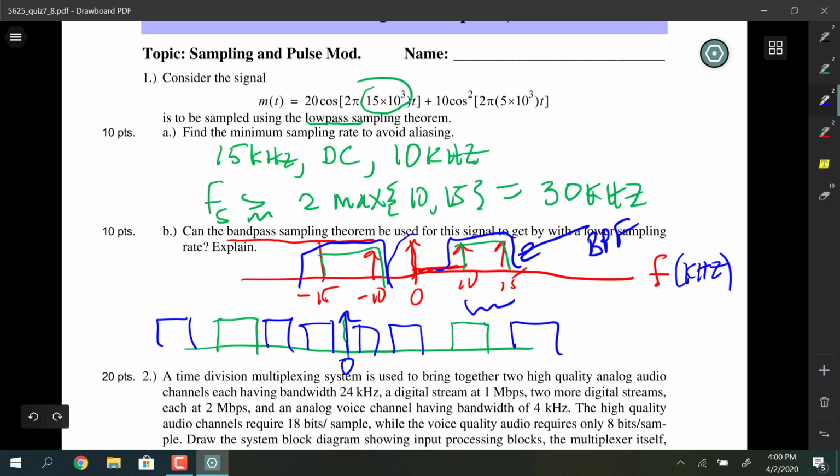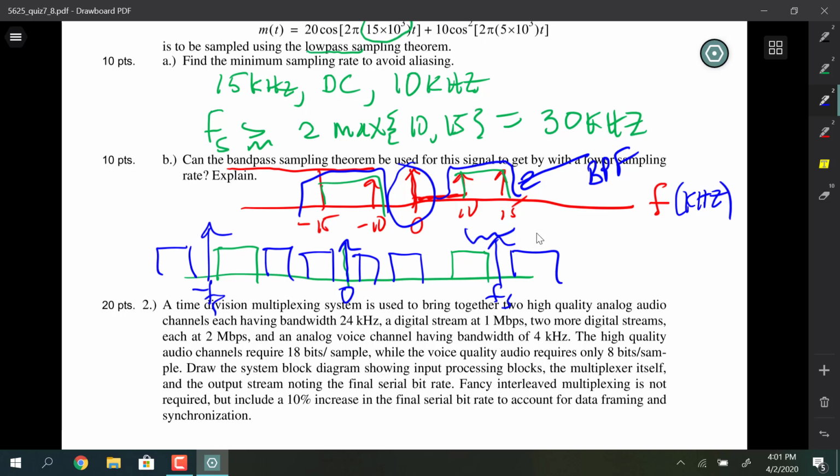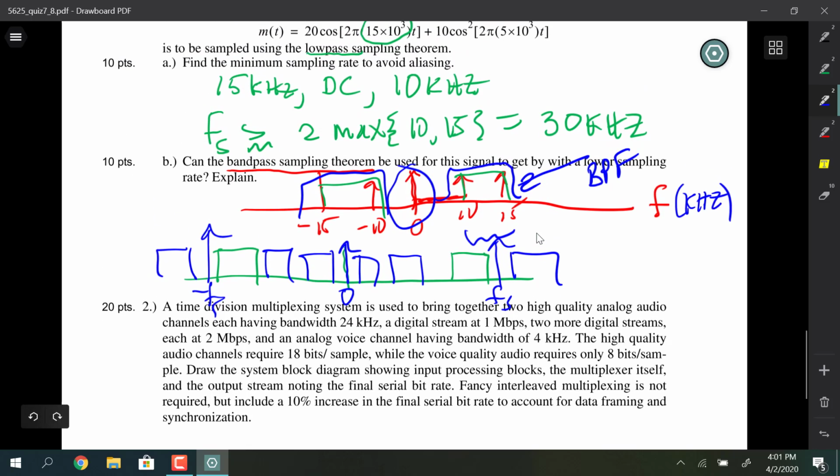In the case of having DC, though, you wouldn't really be damaging anything because it's not going to translate to anything but an image, a multiple of the sampling rate. Whenever we have sampling theory, this thing would repeat itself right over here. This would be like Fs minus Fs. The DC images again at Fs and 2Fs and so on. I don't want you to get too hung up on that, because at this point I was referring to the textbook, and strictly speaking, the answer is no.